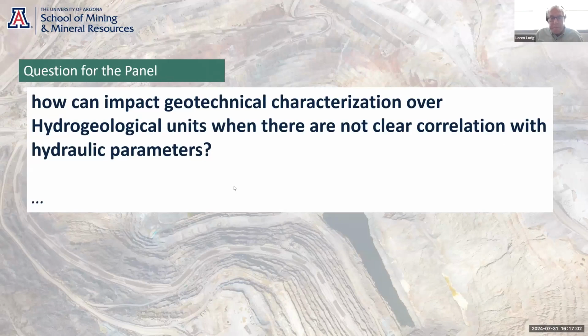Yeah, you have to interpret all the data sets appropriately too, right? Just because there's a high fracture frequency in a rock mass, it doesn't mean it's permeable. If all those fractures are filled with clay, then it's impermeable, right? So you have to look at all the available data sets and make sure you have a complete understanding. Same with RQD, right?